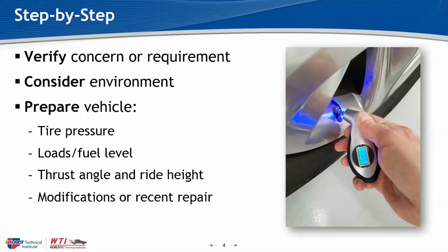Randy had a good example. We're at the research center with tire pressure. I believe it was the driver's front tire that was low. That's correct, Keith. Driver's front tire low, and only by about 8 or 10 pounds. Right, and they made a laser mark on the vehicle of where the center line was, and then they properly aired the tire up, and there was, what'd you say, almost a quarter of an inch or more of movement? Almost 3/4 of an inch of movement. So you can imagine at a distance how much that changes. And when we get to the thrust angle, I'll give you some numbers of how big a small variance could be affected at a distance.